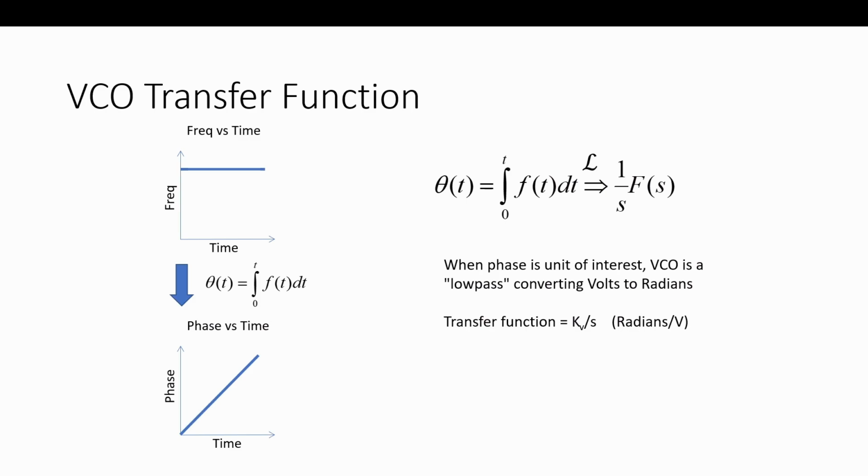It's going to respond proportionally to a phase difference, not to a frequency difference. We use that component, then it is a phase-locked loop. And in that case, our model of the VCO has to be in units of phase to go into that phase detector. It's in the loop model. It doesn't change the implementation. It's just in the loop model, right?